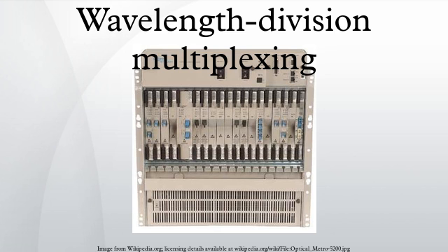Many systems will offer 2.5 Gbps transponders, which will normally mean the transponder is able to perform 3R regeneration on OC-48/STM-16 signals, and possibly gigabit Ethernet, and report on signal health by monitoring SONET/SDH section layer overhead bytes. Many transponders will be able to perform full multi-rate 3R in both directions. Some vendors offer 10 Gbps transponders, which will perform section layer overhead monitoring to all rates up to and including OC-192.